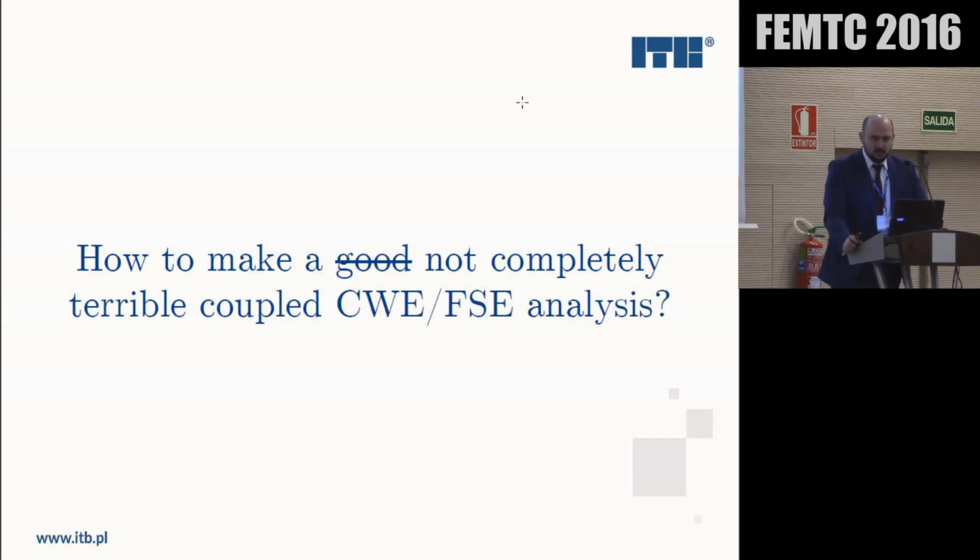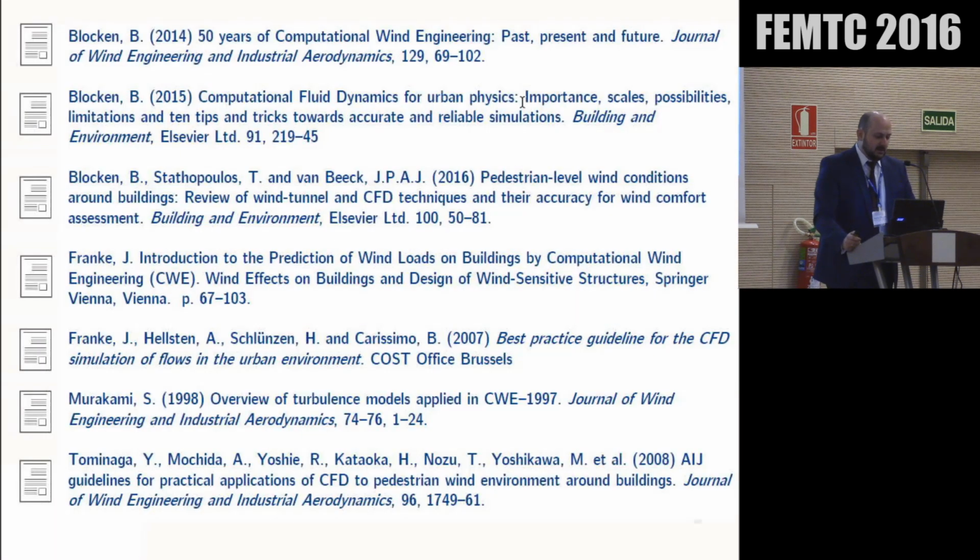You have to know a thing about wind engineering. There's a saying among wind engineers that CFD is wrong until proven otherwise. It's a little different from what fire engineers think: as long as it's colorful, it's good. But wind engineers really don't trust CFD as much as we do, and they put much more effort into making sure that it's viable. Of course, we're not able to reach the same level when we try such a complex analysis, like using fire and wind at the same time. But we can make it at least not bad.